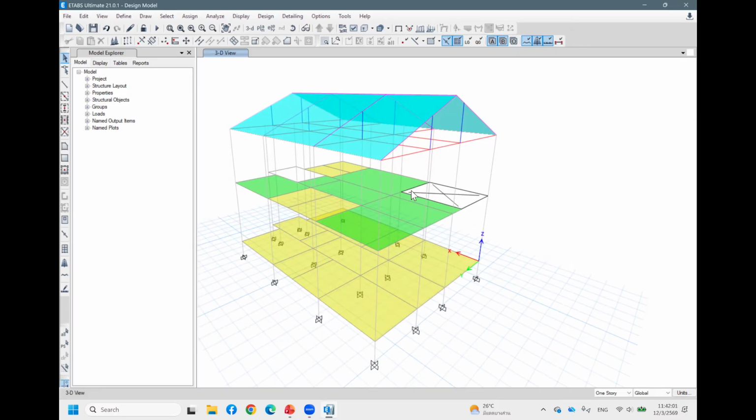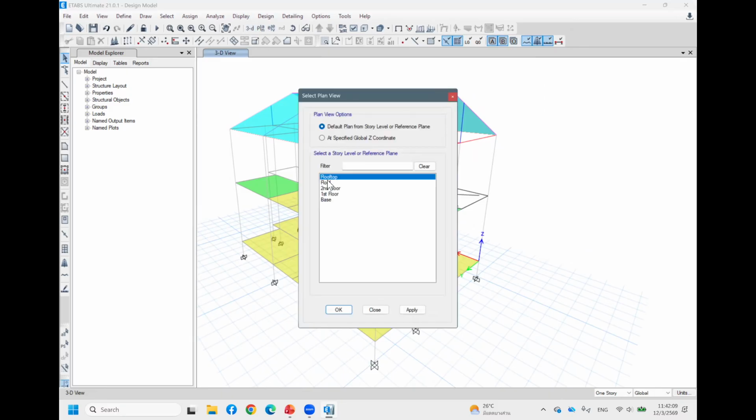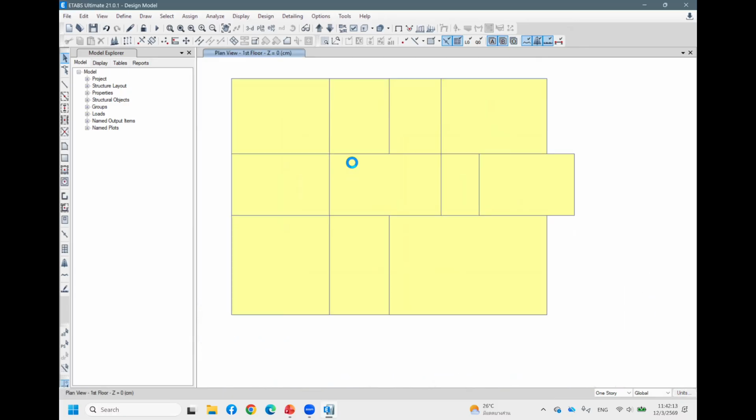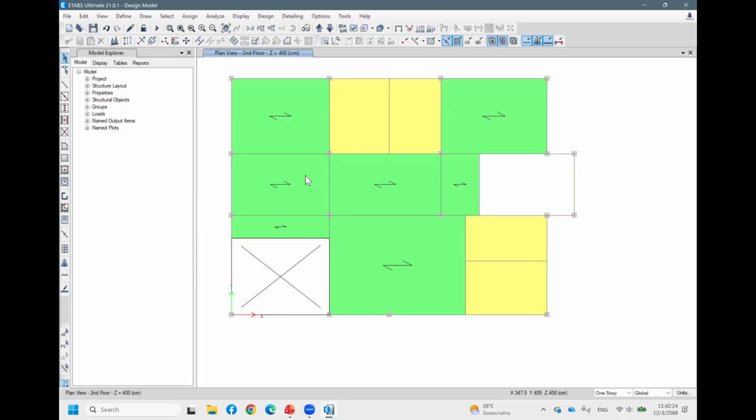Okay. Now we have already assigned the beam and the column, and now let's assign the slab. The slab, first floor. Since it is just RC slab, the load will distribute correctly to the floor. But now go to precast slab. You can see the direction here. The precast slab will transfer the load in the direction of this. So if we don't want it to transfer the load like this, we can change it. So I will change this load.